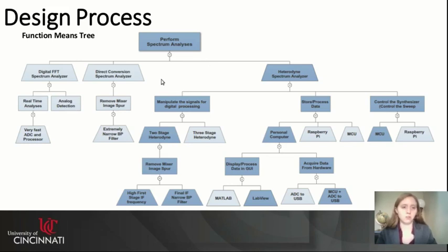In our initial research, we found that the digital FFT and direct conversion spectrum analyzers were not really feasible as a senior design project as they required very costly components. So we instead decided to look at the heterodyne type spectrum analyzer. Our spectrum analyzer also has to perform other functions, including manipulating the signals for digital processing, storing and processing the data, as well as controlling the sweep.